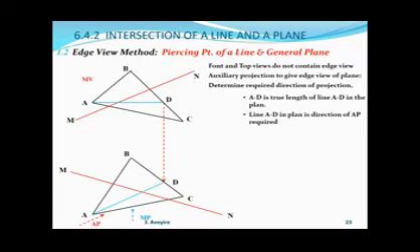So that is MP. Now we intersect a reference line, XY, at a convenient point, which gives us positive and negative measurements. So here, that is inserted through the point C. So X, Y through the point C. Points in the direction of VP above XY are positive, and points in the opposite direction from XY will be negative.